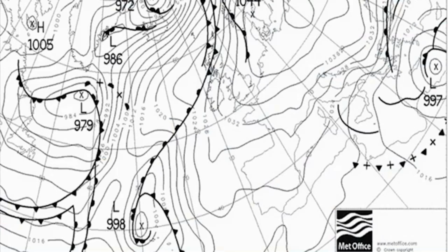Unfortunately, the relationship between pressure and height is not a linear one, so that calibration of the altimeter scale is not a simple matter. The situation is further complicated by high and low pressure weather systems, which produce pressure differences in the horizontal plane. Furthermore, the temperature of the air at the surface and the temperature lapse rate in the air above vary considerably, and this affects pressure.